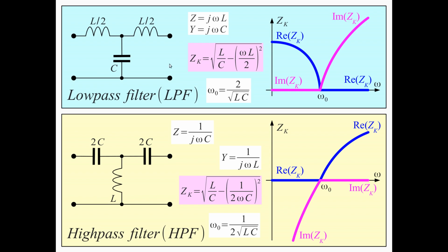This low-pass filter is already something that is very much required when we have analog to digital conversion. It is a required component for analog to digital conversion if we want to do any digital signal processing. We also need a low-pass filter at the output of a transmitter to avoid radiating harmonics. We need a low-pass filter in optical communication to limit the wideband noise of our electronics. So the low-pass filter is frequently used. The high-pass filter is also required for some applications.